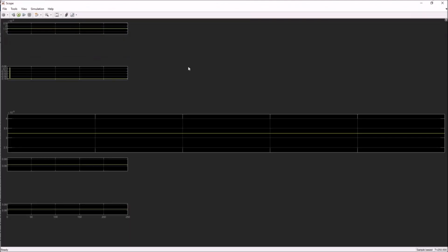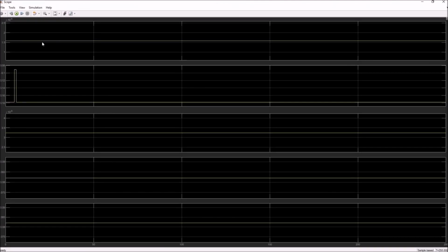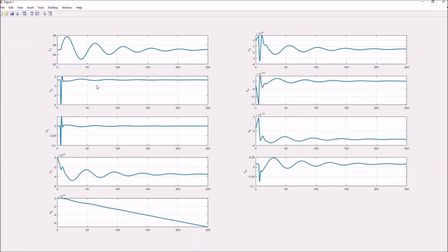So again, let's pull this over. And as you can see, we are just using the trim values of the control, except at 5 seconds where I hit the tail for 1 second with this 5 degree pulse. And here is now the response of the system. We're flying along hunky-dory for 5 seconds, and then we whack the tail surface. We excite some modes, but the vehicle does come back, and after 4 minutes or so it starts settling back to a trim point.